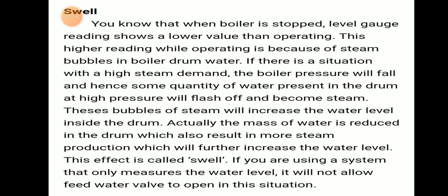Swelling means this: when a boiler is stopped, the level gauge reading shows a lower value than when operating. The higher reading while operating is because of steam bubbles in the boiler water drum.